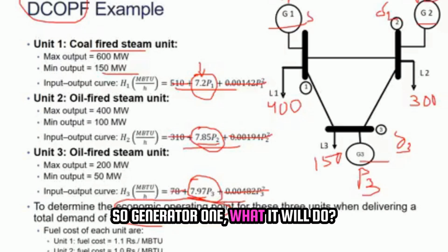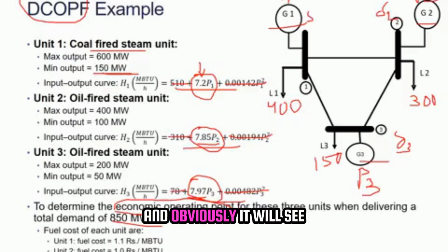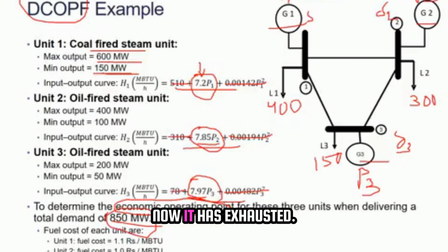Generator 1 will start generating, increasing its generation from 150 because its minimum limit is 150. It will keep on increasing, and it will reach 600, but it will still not be able to satisfy the load of 850 megawatt. So this generator PG1 will generate at 600 megawatt. Now it has been exhausted. There is no more power remaining with generator 1.